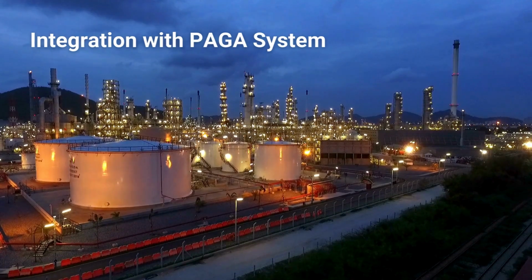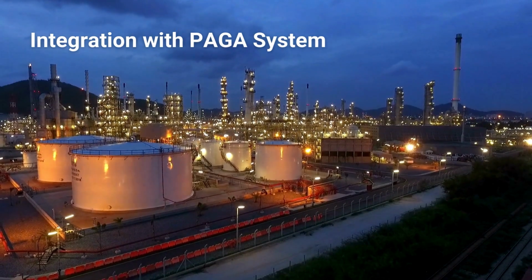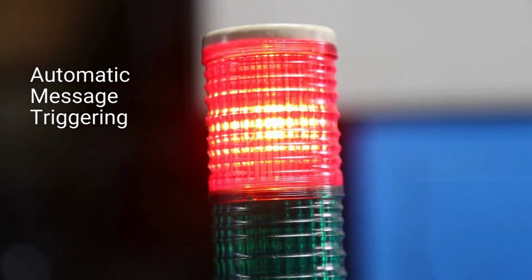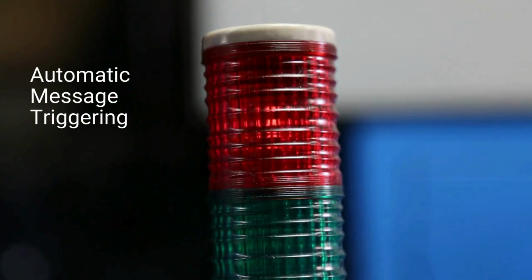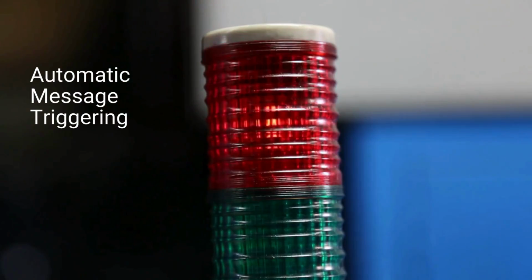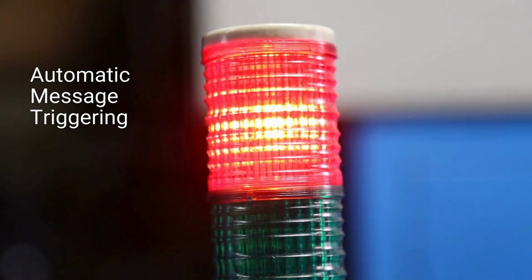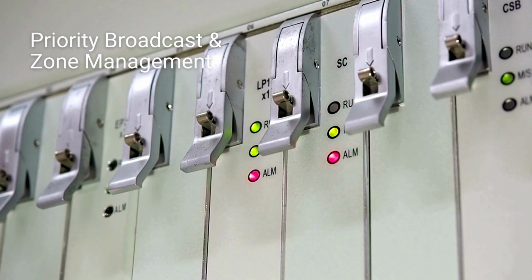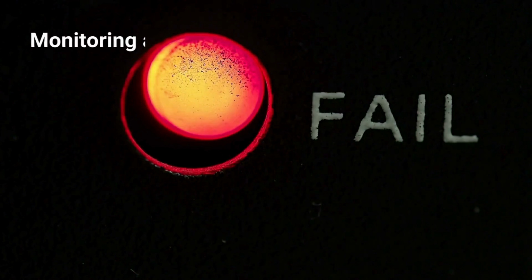The EVC system integrates with the PA/GA system to ensure that emergency messages can be broadcast to all personnel across the facility. In many cases, the EVC system can trigger automatic PA announcements during an emergency. Automatic message triggering is when pre-recorded emergency messages can be activated if an emergency is detected by the EVC system. During an emergency, the EVC messages take priority over standard announcements to ensure that critical instructions reach everyone promptly. Zone management allows for broadcasting to specific zones or the entire facility, depending on the nature of the emergency.